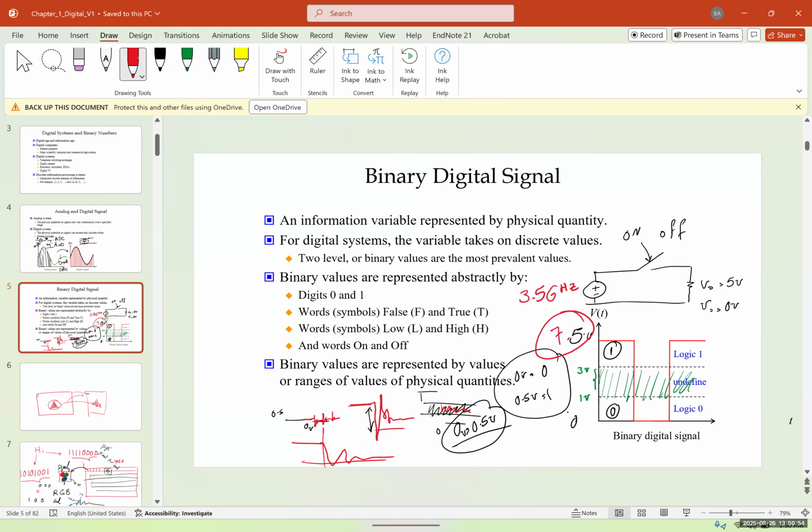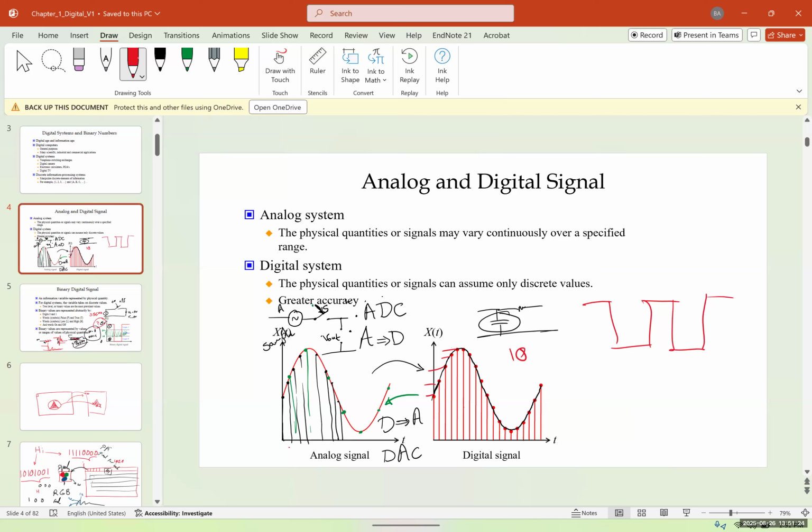Now that we learned about digital and binary signals, let me give you an example of where we use the digital signal. So as mentioned, one way is to use it in sound waves. By the way, this one that I spoke about has multiple levels. So instead of binary, we may have 10 levels. A binary only has 2 levels, so zeros and ones and zeros and ones, okay? But if instead of 2 bits, we have 4 bits, you're going to have 16 levels. If you have 10 bits, you're going to have 1024 levels. And I'll explain more about this.